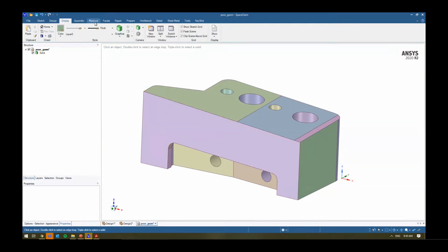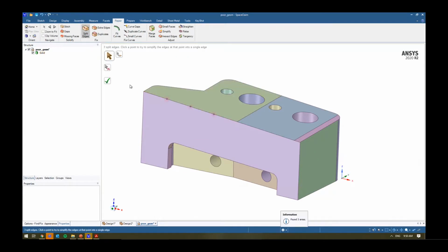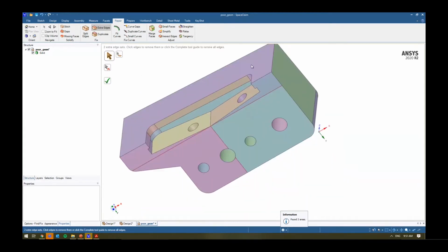You can even go to the display. That's right. So the problem with that, you notice we've got a couple of edges. The problem with that is that the mesher might have problems generating these fine elements across here, or you might be splitting unnaturally around some of these edges. So generally going in and fixing the split edges, getting rid of the vertices.